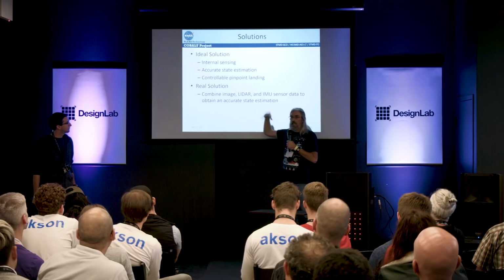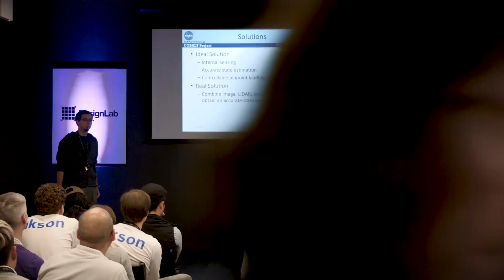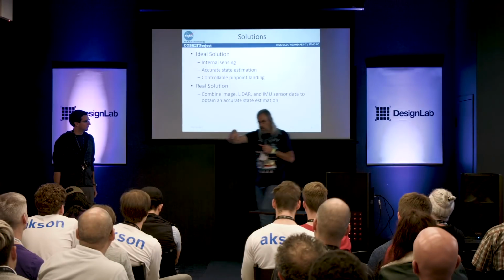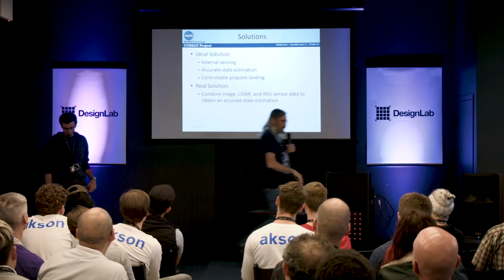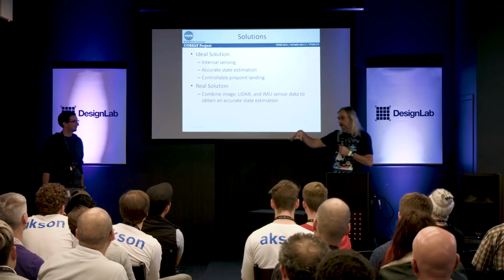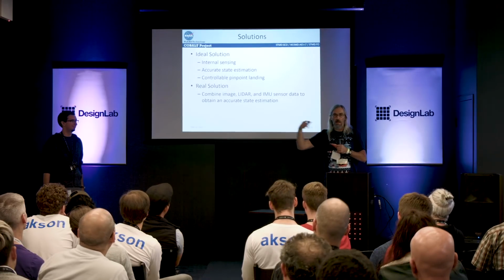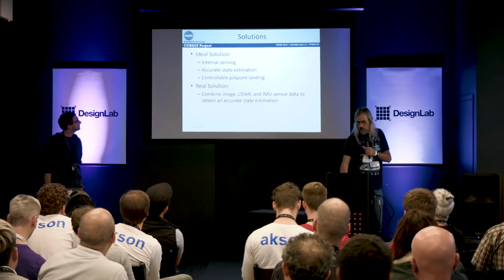And the LiDAR is actually a Doppler LiDAR, so not only does it tell you I'm this distance from the surface, if you're sliding across the surface at a constant altitude, it can measure the velocity that you're doing. And that lets you measure something that right now we're kind of doing with inertial navigation alone.